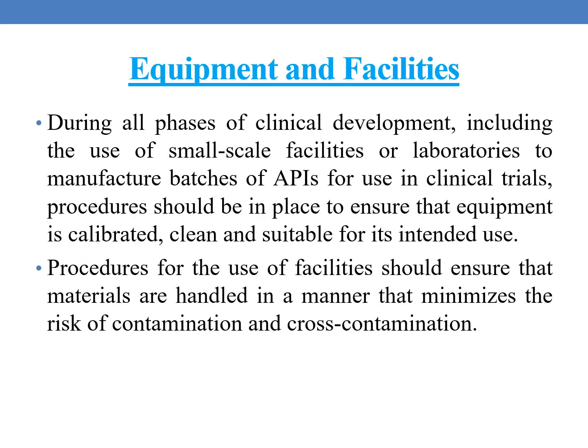Coming to equipment and facilities. During all phases of clinical development, including the use of small-scale facilities or laboratories, to manufacture batches of APIs for use in clinical trials, procedures should be in place to ensure that equipment is calibrated, clean and suitable for its intended use. Procedures for the use of facilities should ensure that materials are handled in a manner that minimizes the risk of contamination and cross-contamination.